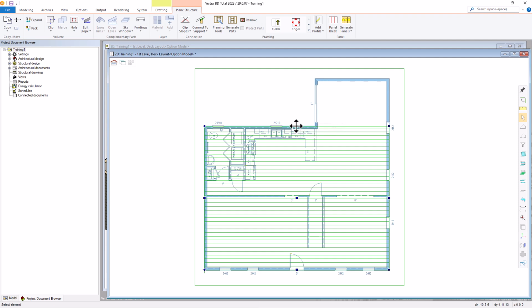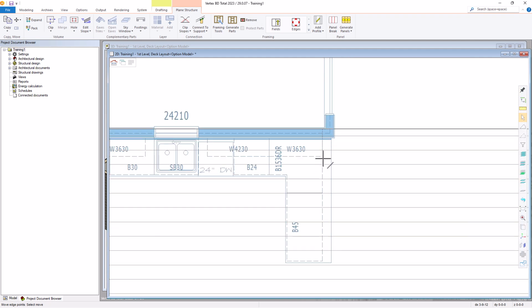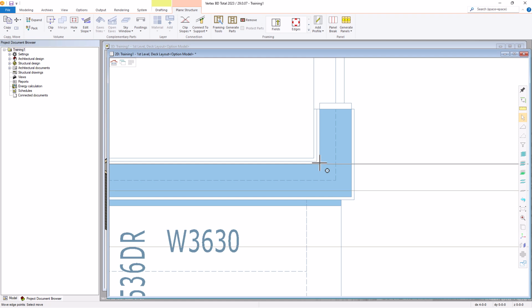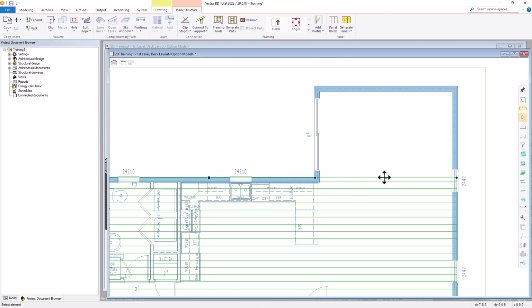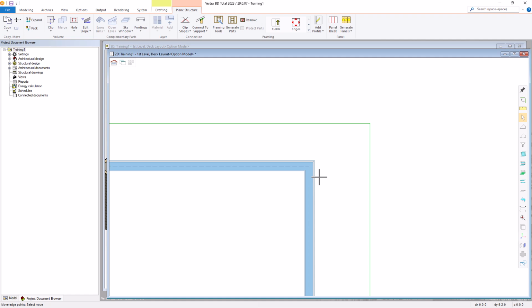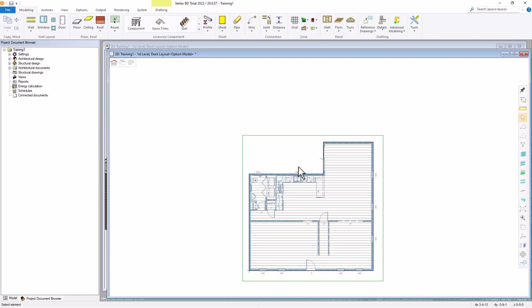Select the boundary, right click over the top of that midpoint, add a point right there along the intersection. And then I can grab that midpoint, stretch it, and bring it up to that corner. And now we created that exact same shape. So it's easy to manipulate a boundary, change it. So if you have any modifications, you don't have to delete it and restart. You can always modify it by adding points or removing points and creating the shape that you need.